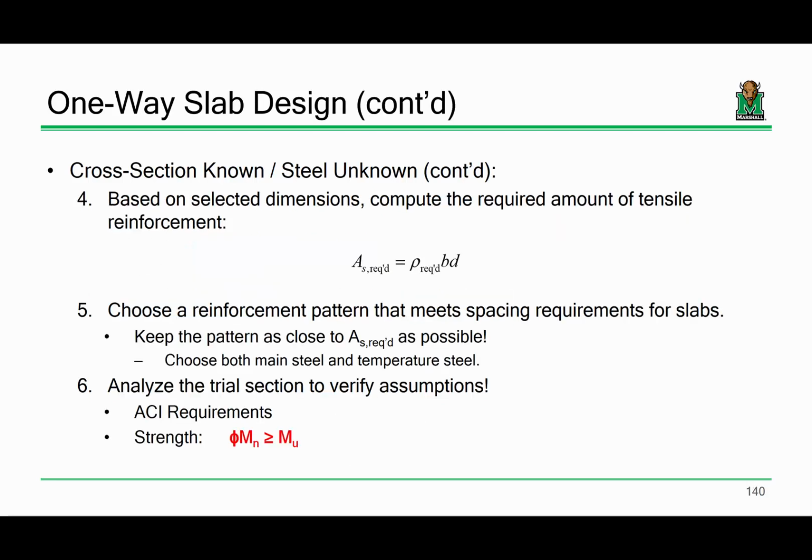The only thing that's different other than that are three things. One, your moment requirements are a bit smaller. So if you get a bending moment of like 10 foot-kips, that's okay because you're talking about a slab. So the tributary area is very, very tiny, and you're only talking about a beam that's this big. So it's okay if the moments are small. Two, you are not sizing one set of reinforcement. You're sizing two. One being the main steel, the actual steel required for the strength of the section. Then you're also sizing the temperature reinforcement. Okay. The third is this.